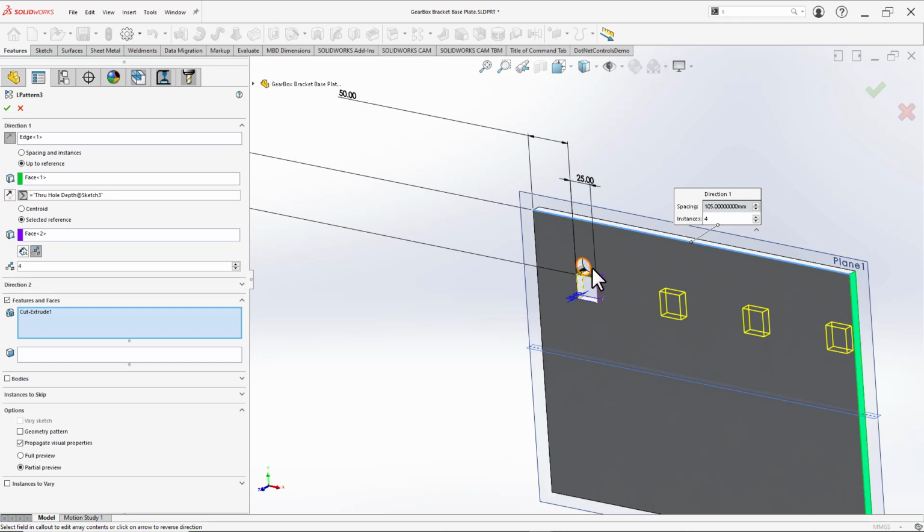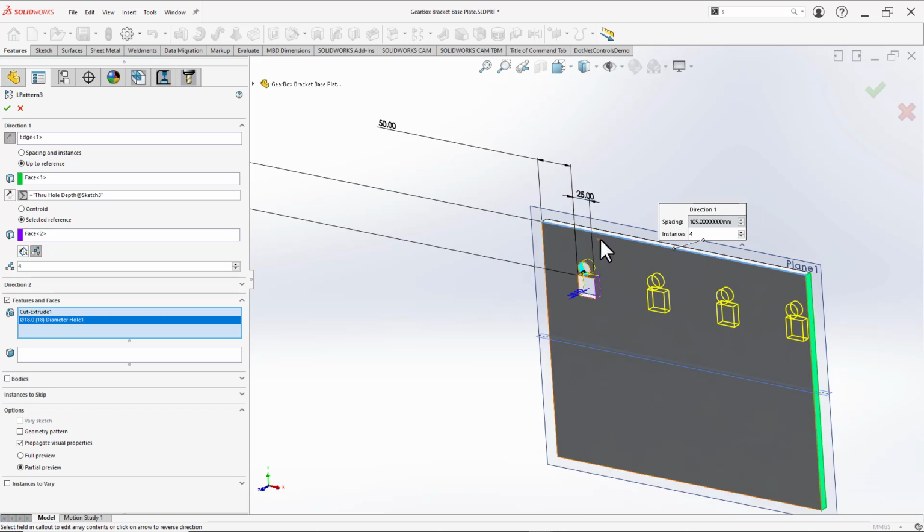Yeah, all right. So that feature is selected now, but deselected that one. Anyway, you play with these selections here, but at the end of the day, all you want is to get SolidWorks to show you that reference offset, that reference dimension. So you type in equation here, and then you select that dimension from the sketch. As simple as that. If you know the name of it, so in this case it's D1 at sketch 4, you could have just simply typed it in.